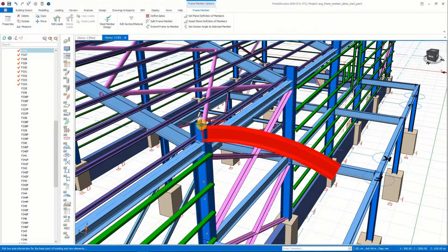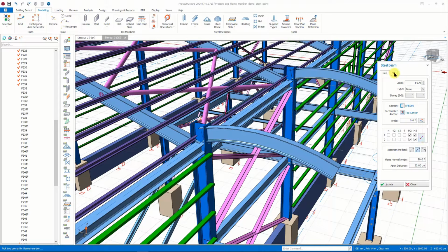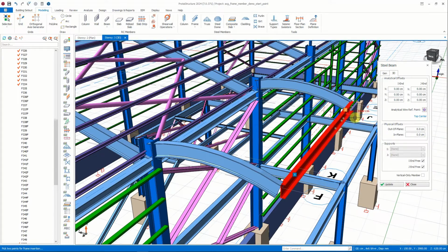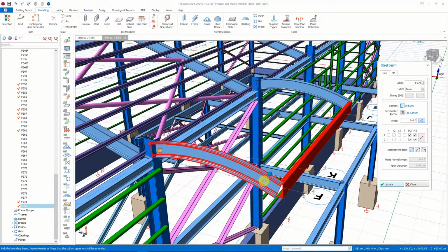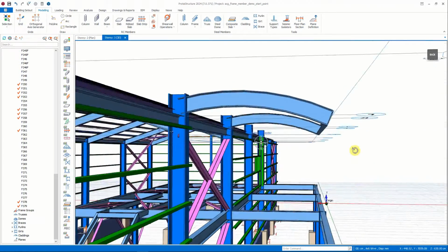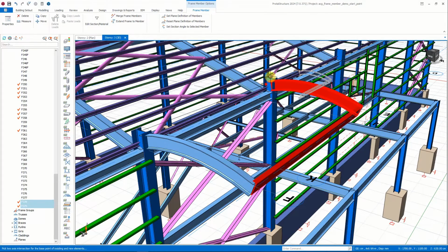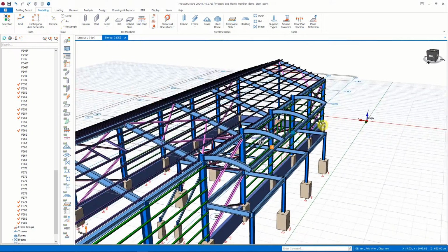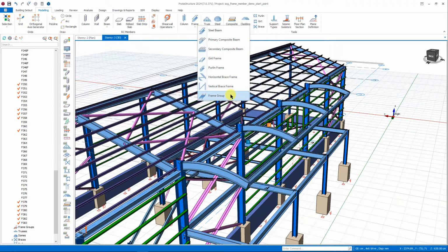We copy the beam to the next column using the column ends as reference points. At the I-end of these beams, we will insert another frame member. Copying all these members, we complete the main form of our cantilever canopy. Now, let's insert frames between these beams to enhance the stability.